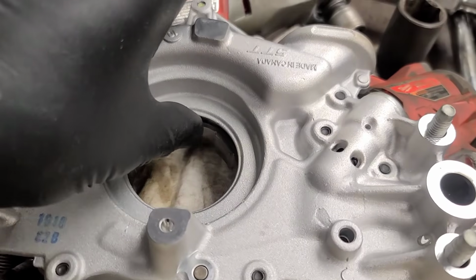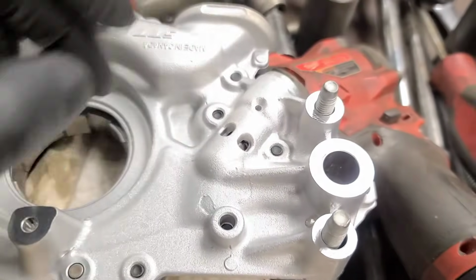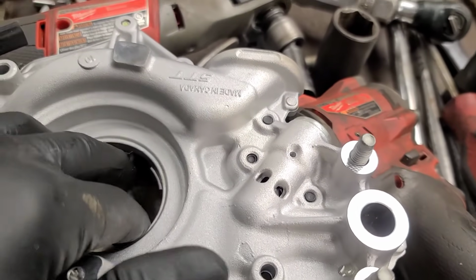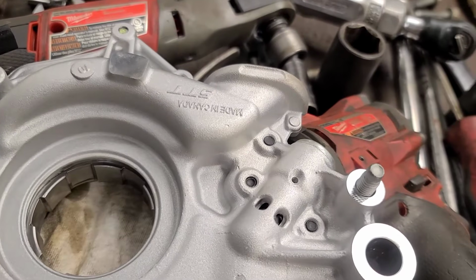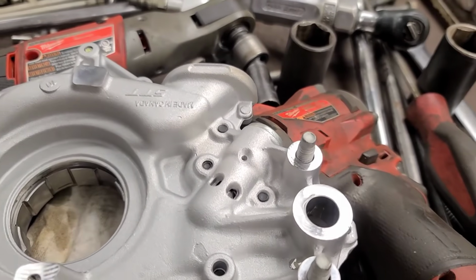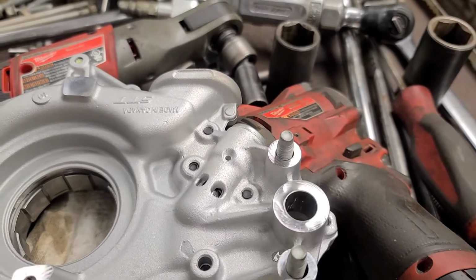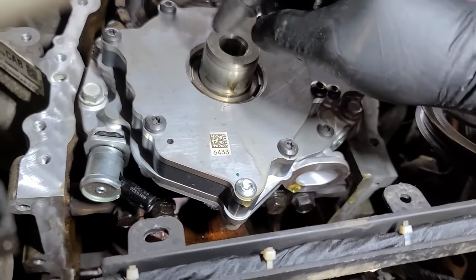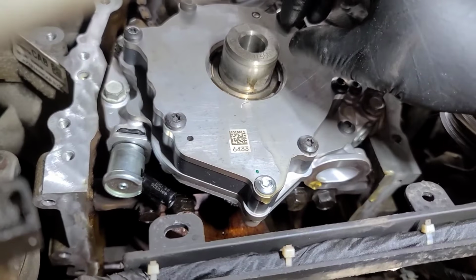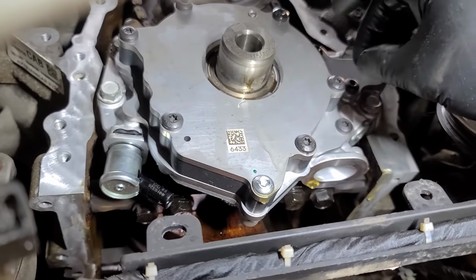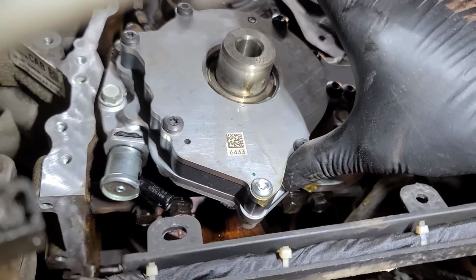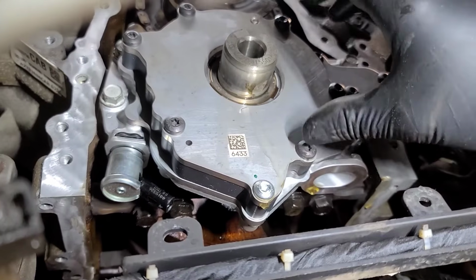So I pre-lubricated it by pouring some synthetic gear oil into this port, which is the outlet port of the pump, and turning the pump several revolutions so that everything is lubricated in there. You could use motor oil, I suppose, but I use the synthetic gear oil because I don't think it'll leak out as fast. So use a small screwdriver to line up the pump drive wheel gear to the actual crankshaft nose, or actually crank gear. And these bolts are 18 foot-pounds. The service literature says push upwards on the pump as you're tightening the bolts up.